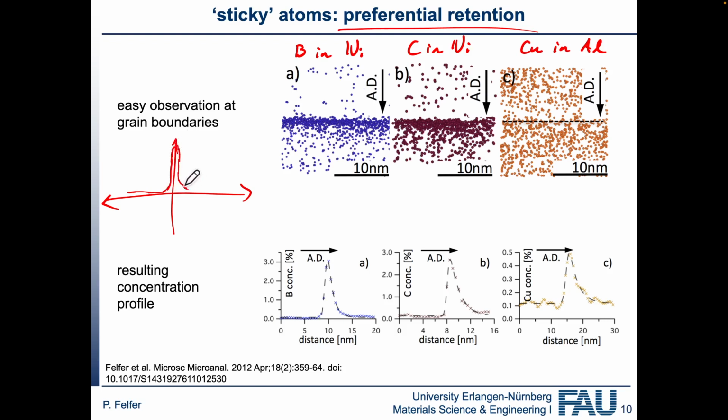We to date don't necessarily know exactly what it should look like. Should it be some Gaussian distribution? Should it be a delta function of atoms just sitting in the grain boundary plane? We don't necessarily know. All we can do is some DFT simulations to get an idea, but then it becomes a little bit difficult to also assess the effect of strains you might have locally. What we can be fairly certain of is that it's probably going to be symmetric, and even if it's asymmetric, we should observe the longer tail up or down at about the same frequency. So half of the specimens should probably have the segregation pointing upwards and half downwards.